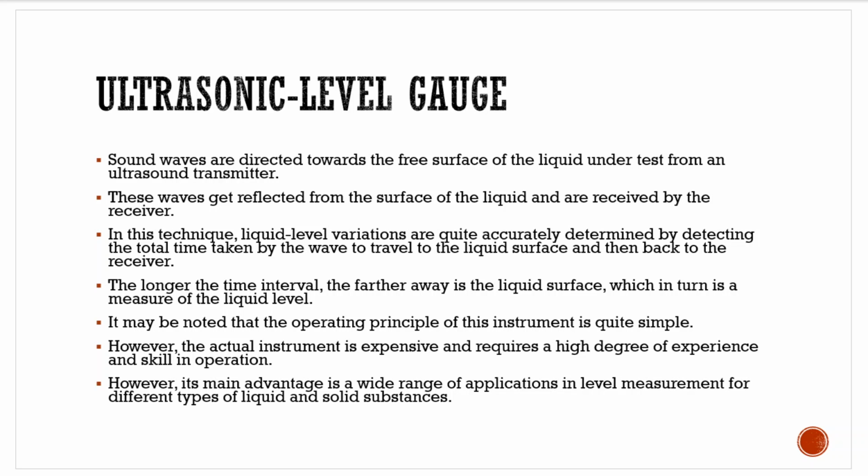So this particular application helps us determine the level of the liquid surface. We are installing this on top of the vessel so that we can measure the distance the ultrasonic wave has to travel. That will give us the height of the liquid.